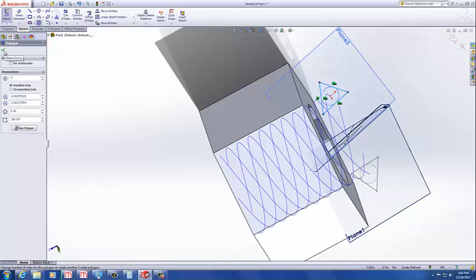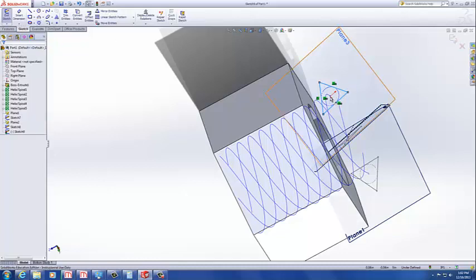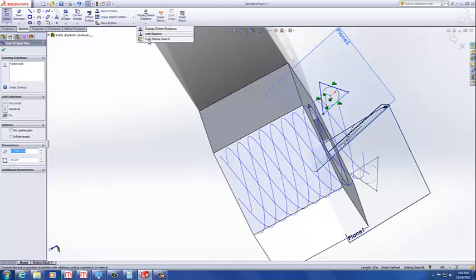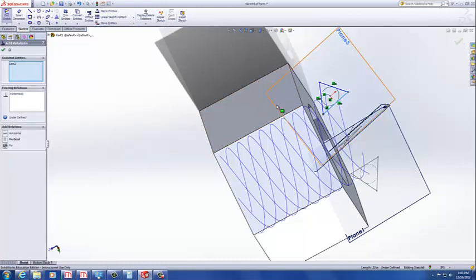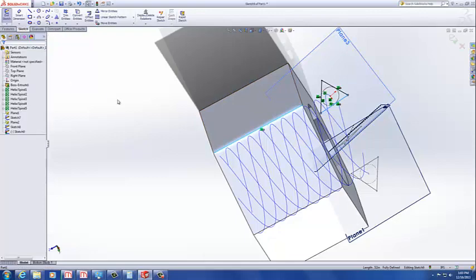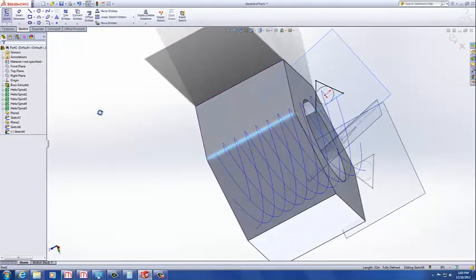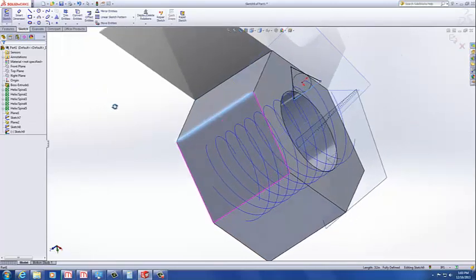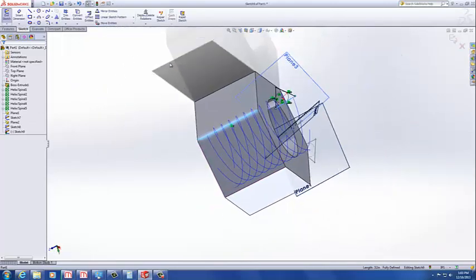There you go. Fix this point. Fix the point, fix the circle, grab your line, add a relation, select this, make them parallel. Now, my part has vertical lines in it. If you're making a part that has a circular body with no vertical lines, you can use construction geometry to put your part together.